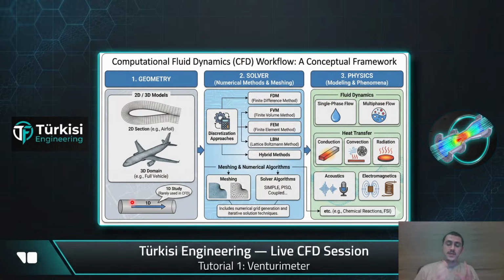So it is highly recommended to start by sketching and thinking about your physics. Sometimes you don't need CFD. Your problem does not require CFD. After you are sure that your problem requires CFD, say we pick single phase flow, for example, I want to simulate an airfoil. I want to investigate the lift forces and the coefficient of drag. I don't want to take the entire wing geometry. Just a cross-section view of this wing can help us to understand the coefficient of drag and lift forces.